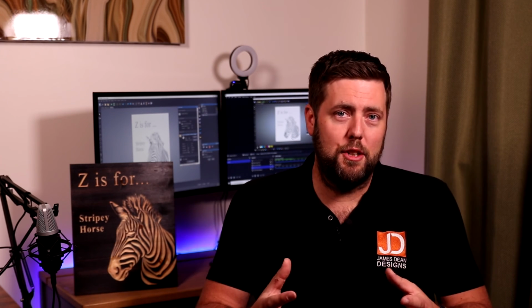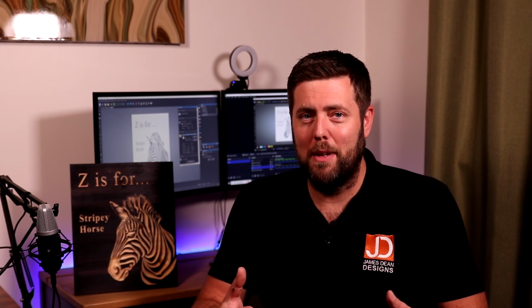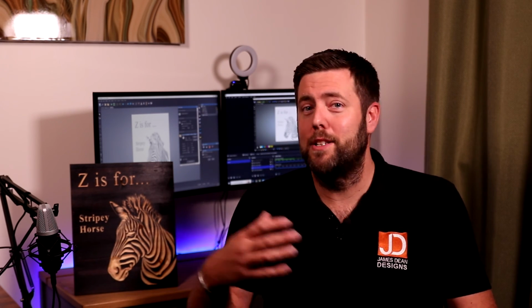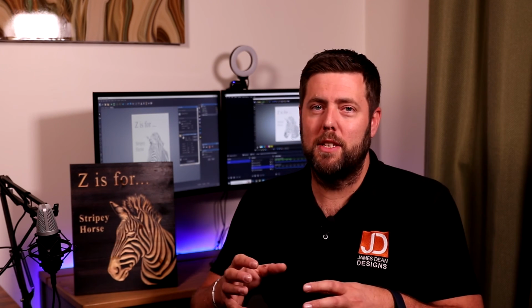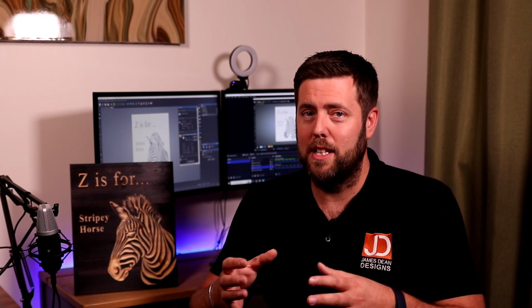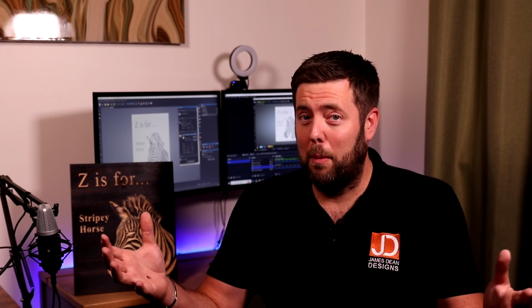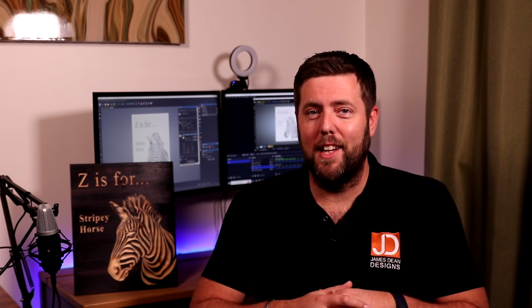What I would strongly suggest is go through your tool database and select different ones and simulate them. Select a 90-degree bit, simulate it, see what the results look like. Select a 60-degree V-bit, do the same. Start to gauge the different outcomes of different bits on your material, and you'll quickly learn the different effects that each bit will get from certain settings or desired outcomes. So basically, have a play, use the simulator, and see how you get on.